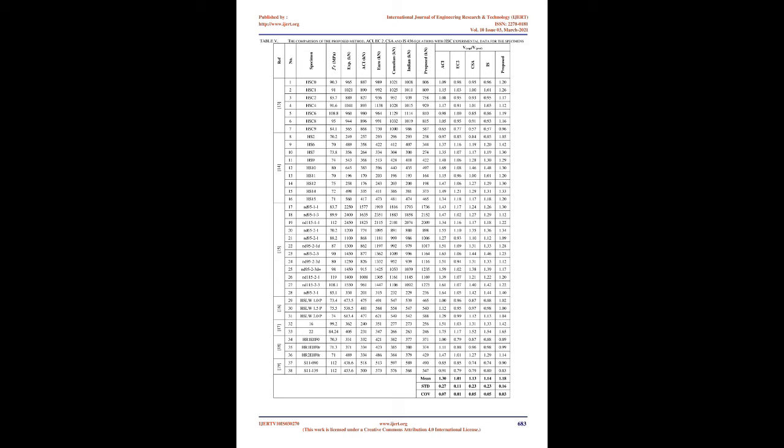B0 equals critical perimeter at distance D/2 from column face. B0 equals 4(C plus D) for a square column, and π(C plus D) for a circular column. C equals column diameter or width, mm. The above equation has R² equals 0.98.